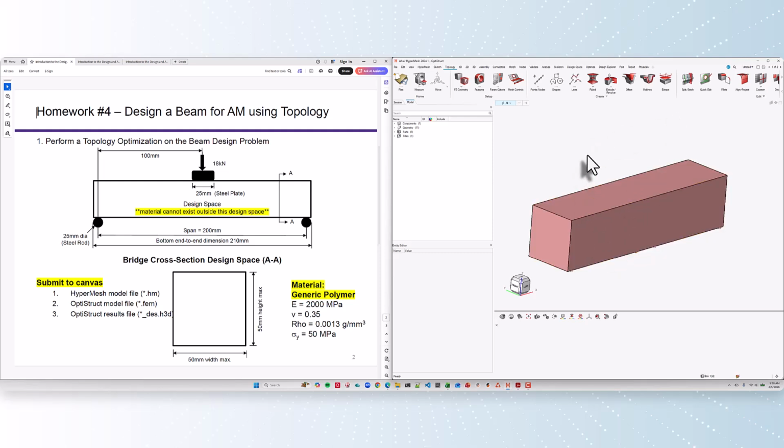I need to trim this solid so that it has edges where I need them. And so we'll go into the trim tool on the topology ribbon. And here we get a lot of options, but the option that we want is we want to split. And then what is it we want to split? We want to split solids. Then I can pick the solid.